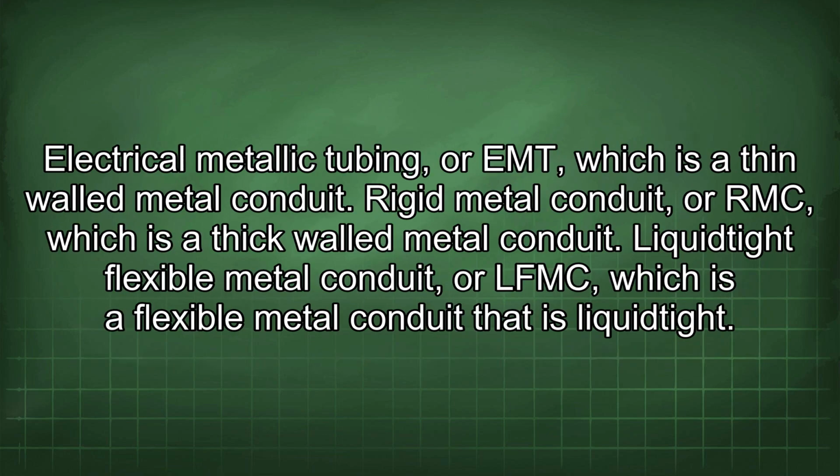Electrical metallic tubing, or EMT, which is a thin-walled metal conduit. Rigid metal conduit, or RMC, which is a thick-walled metal conduit. Liquid-tight flexible metal conduit, or LFMC, which is a flexible metal conduit that is liquid-tight.